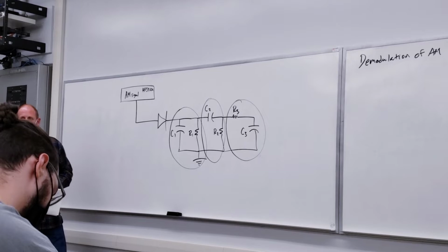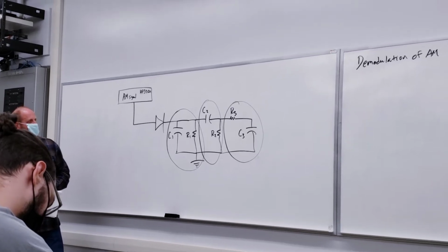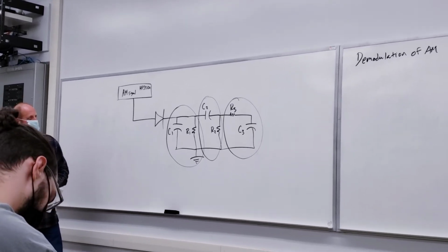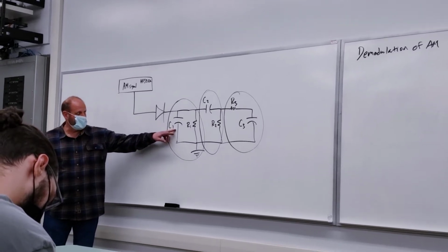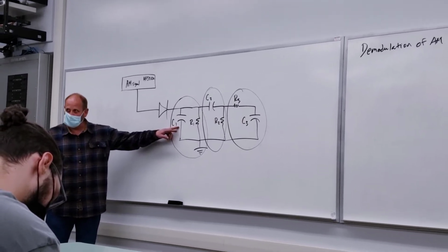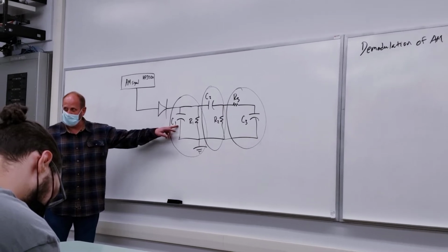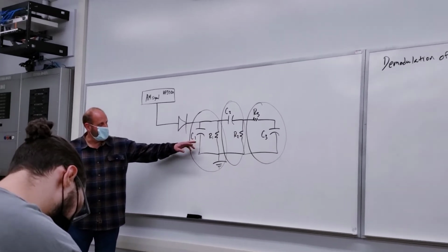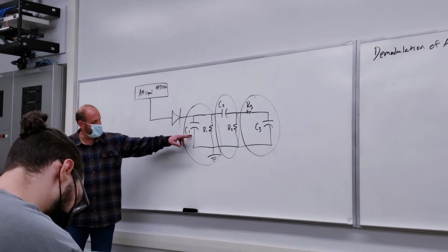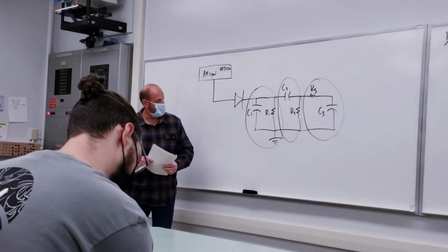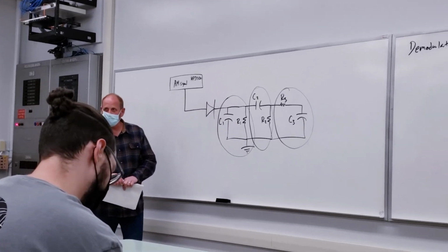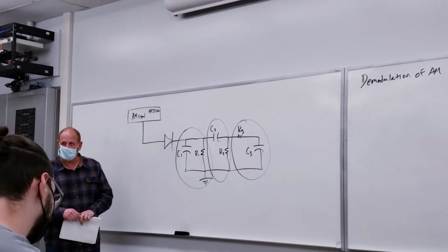If you look at these different stages, you can kind of see what they are. First order filters are easy to figure out because you just know that at high frequencies, the caps turn into shorts, right? It just turns into a wire. So this first stage, at high frequencies, it shorts out. That tells us it doesn't pass the highs. It's a low pass filter.